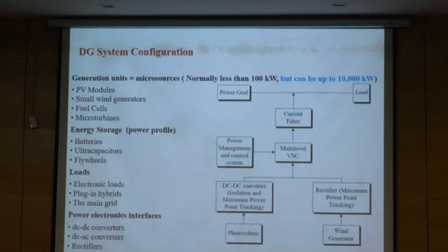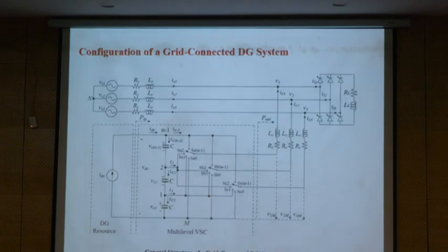This part is the system we have, but what is happening in reality? So we have a DC bus here. We have a multi-level converter, but it doesn't matter, multi-level, two-level, it depends on the voltage level and the power level. So we have this interfacing system. We have impedance here. It can be a combination of the filter, transformer, impedance, then we have the equivalent RL here. And then we have a load.